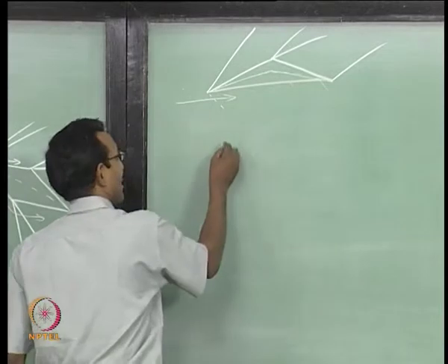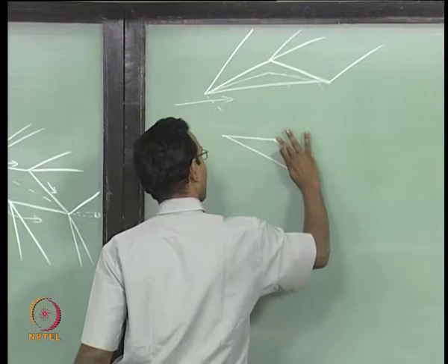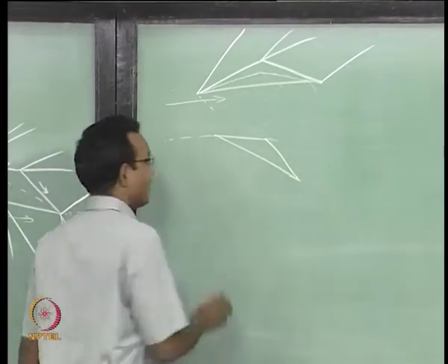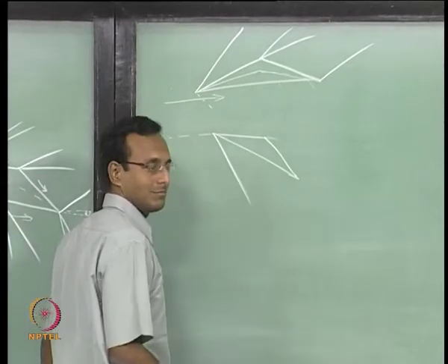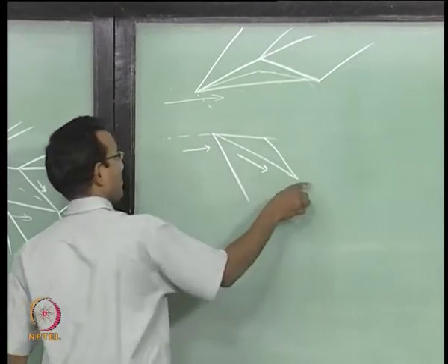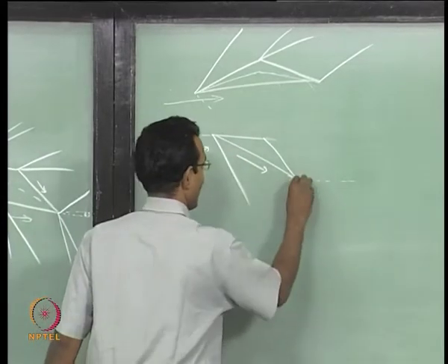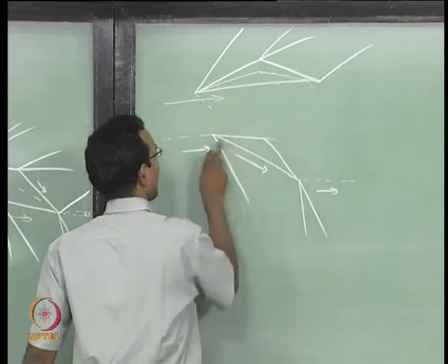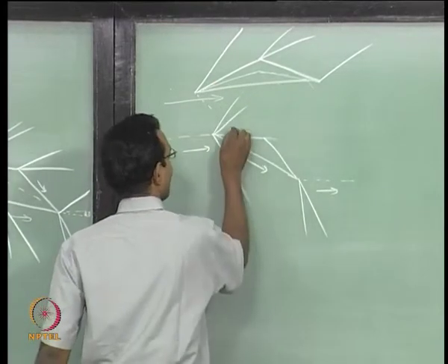If I have any angle of attack, how will you solve this? If I have something like this, same problem as before, I will just draw a dotted line there, and I am going to consider this flow as it comes straight and turns in. So there should be a shock here, and then flow goes here. We know that it is going to have almost 0 angle at the leaving point. So it should be an expansion here, and the flow goes like this. In here, I have drawn it such that it has gone below. So there should be an expansion fan here.